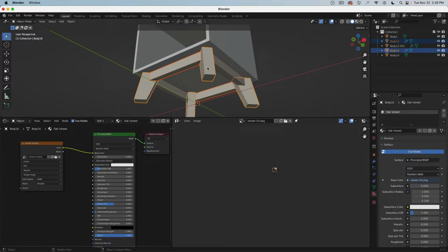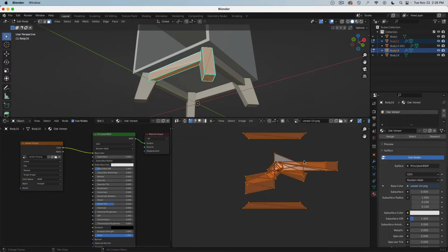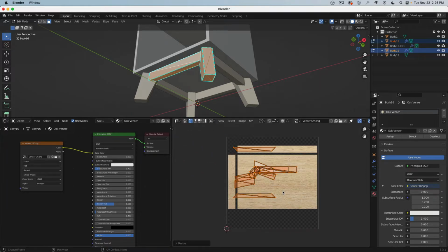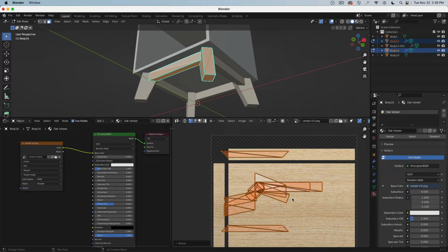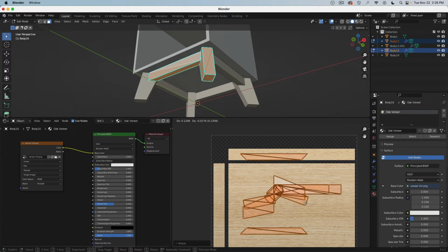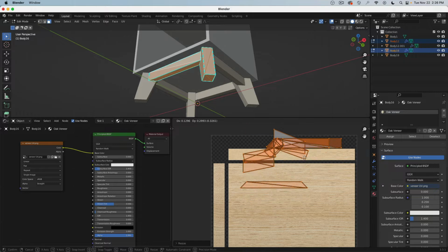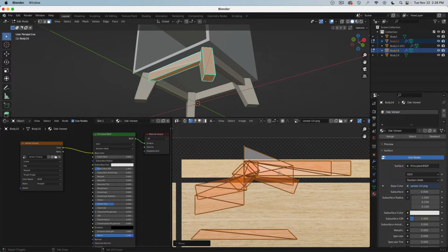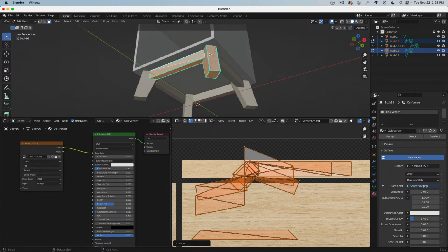We select both objects. Press Tab. Press A. And you see I can now access in the UV editor all the faces of both at the same time. So it's not like scaling one by one. I can scale them more or less equal. And now I know here that this is 2 inches. These pieces maybe are plus minus an inch and a half.